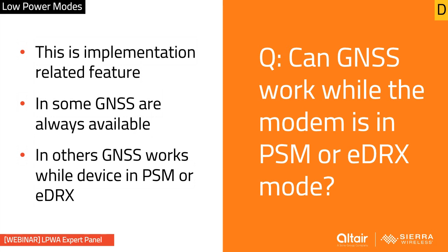Yeah, it's an interesting question, and it is very much implementation dependent. Some solutions would be completely independent of eDRX and PSM. GNSS could work in parallel with both modes, or when the device is active. On the other hand, GNSS can work while the device is in PSM or eDRX, basically in sleep. This can be done by reusing some of the hardware in the device to further reduce the cost of the devices, which is also very important for LPWA devices.